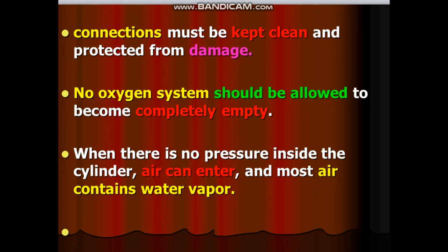Connections must be kept clean and protected from damage. No oxygen cylinder should be allowed to become completely empty. When there is no pressure inside the cylinder, air can enter, and most air contains water vapor.